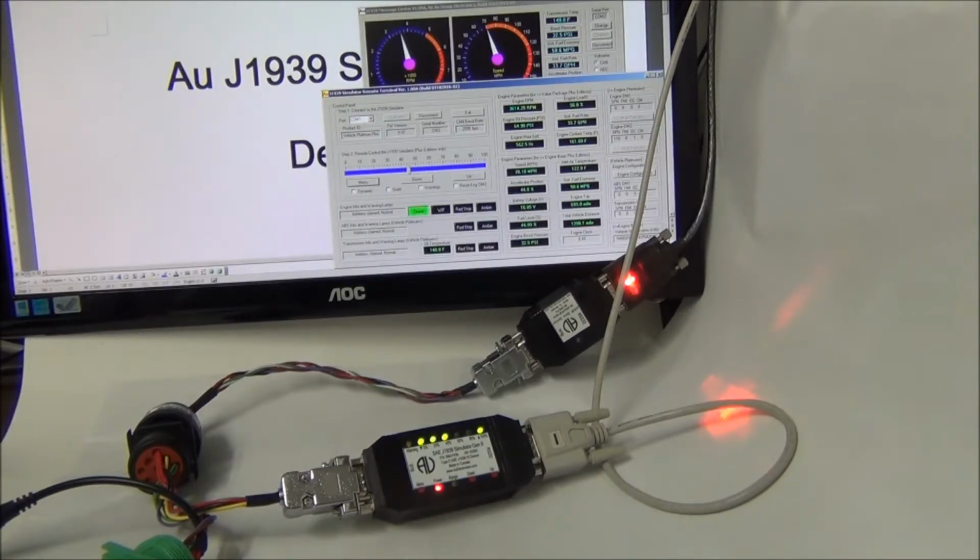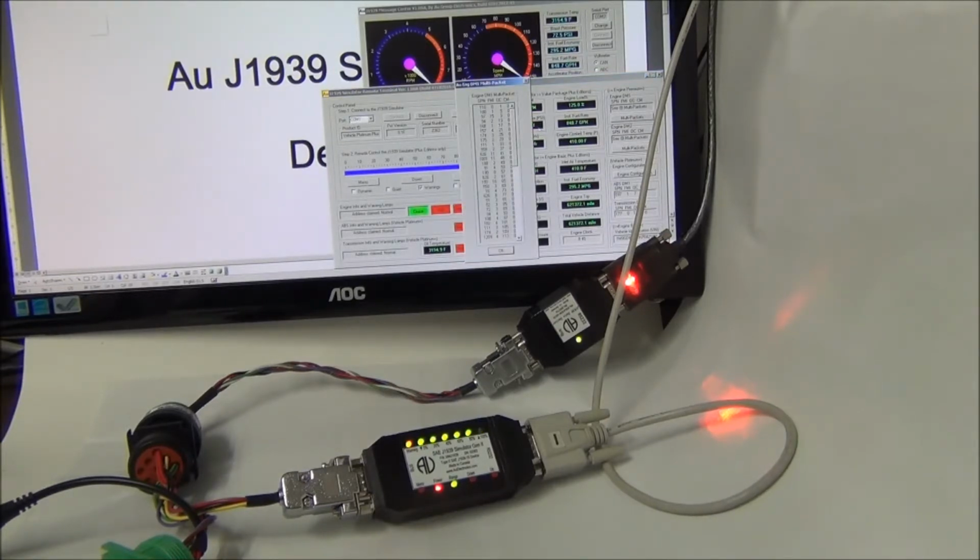So the other area is for displaying the simulated data. If we move the value all the way to 100% and check the warning, you will see the multi-packet for engine DM1 will be activated. Press that button, and the engine DM1 multi-packet information will be displayed. And check this one also. The engine DM2 multi-packet information is displayed.